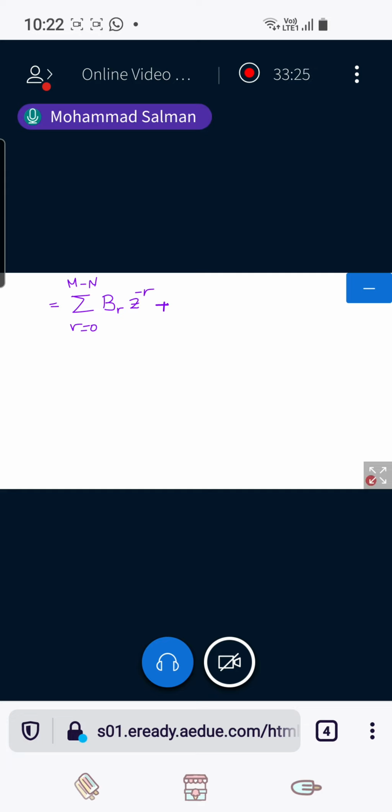And here, let's write it as a summation from k equals 1 up to capital N of a sub k over 1 minus d sub k z to the power minus 1. This is our system in the z domain. But again, remember, my target is h of n, the impulse response, in the time domain. So what is h of n in this case?